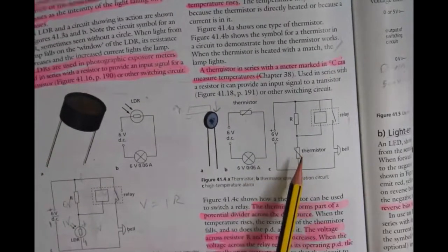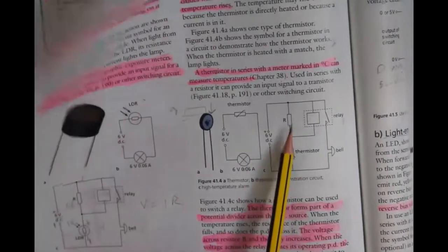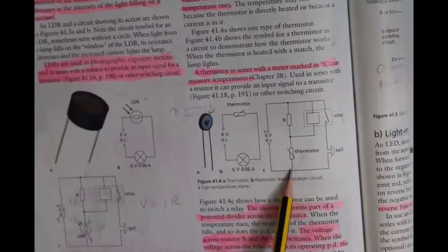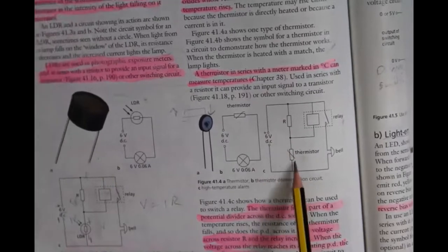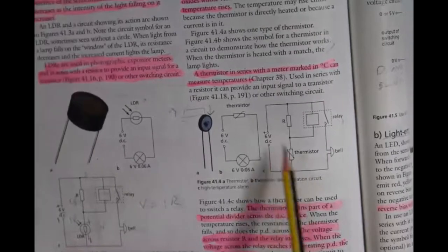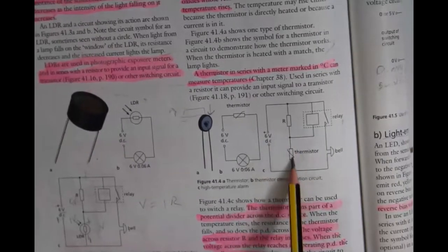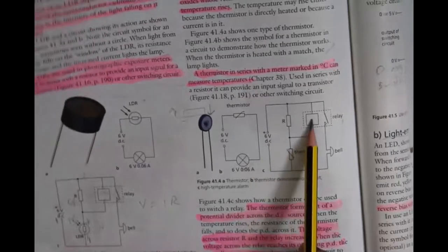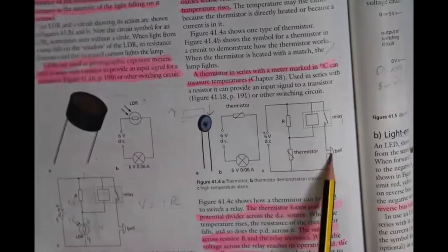As the temperature increases, the potential difference across this resistor increases because the resistance of this thermistor decreases. That means the current can flow through it easily, so there is less potential difference across this thermistor. Of the 6 volts, most of it is going to be handed off to this resistor, with less potential difference across the thermistor because of its lower resistance. Again, this electromagnetic coil is going to get magnetized, pull the switch closed, and the bell will ring.